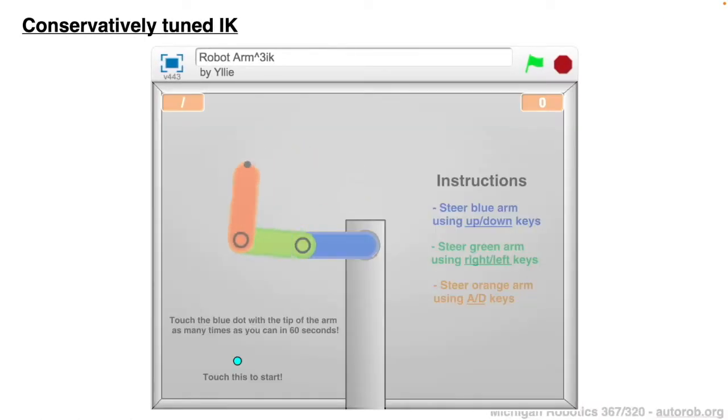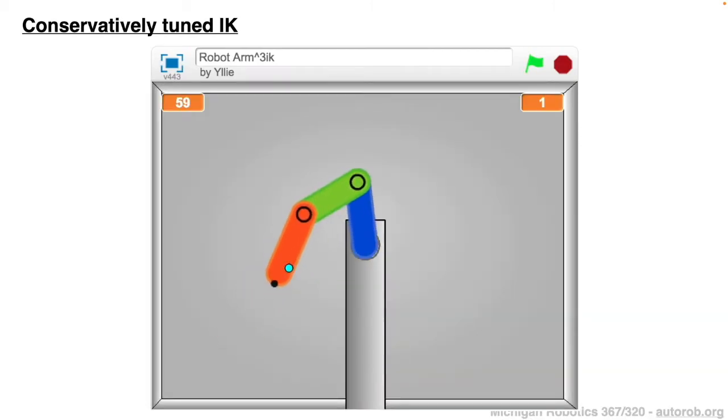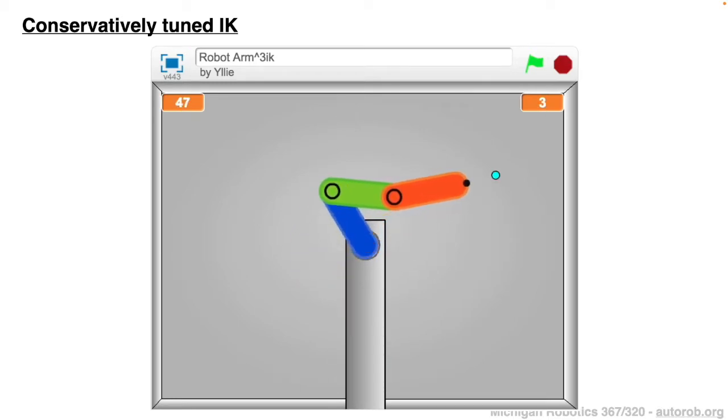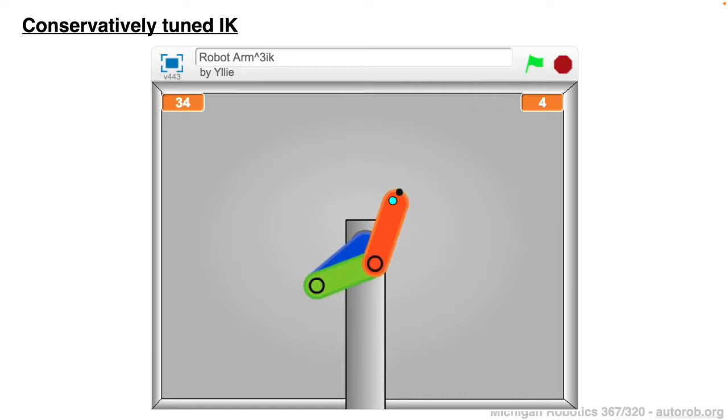So we can still apply inverse kinematics with a more conservative tuning to have very smooth natural motion, which is shown on this modified controller here, where, as is familiar to us from our pendulum example, one of the sacrifices to having some of this smooth motion is that you don't reach quite as many set points in the same speed, but you have much more natural, safe trajectories that the robot ultimately will follow as it tries to reach the set points.